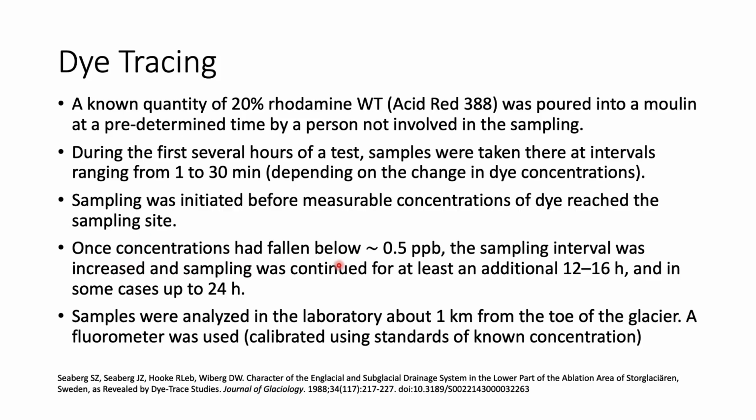Once concentration had fallen below 0.5 parts per billion, the sampling interval was increased and sampling was continued for at least an additional 12 to 16 hours, and in some cases up to 24 hours. So people keep on monitoring how much dye is actually present. Then the samples were analyzed in a laboratory about 1 kilometer from the site of the toe of the glacier.